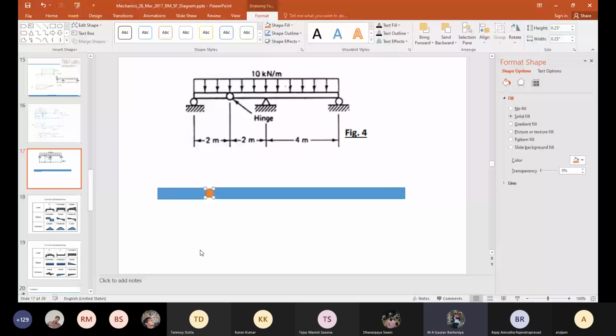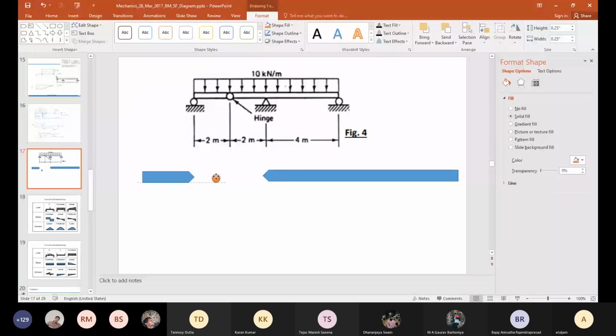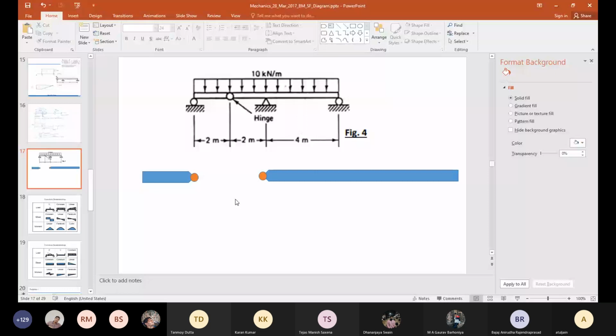So if two beams are joined at the center, you can draw the bending moment diagram of the two parts separately. And as a check, you have to make sure that where there is a pin, the bending moment must be zero. It is actually two beams joined together, and at the point of joining, the bending moment is zero. That is it.